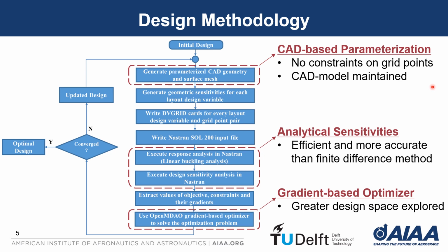Secondly, the CAD model is maintained throughout the optimization process because the CAD parameters are directly controlled by the optimizer. Therefore, the additional step of converting the optimal design back to CAD is not required. The analytical response sensitivities require less computational cost and are more accurate than the finite difference method. The gradient-based optimizer allows a large number of design variables, hence a greater design space can be explored.